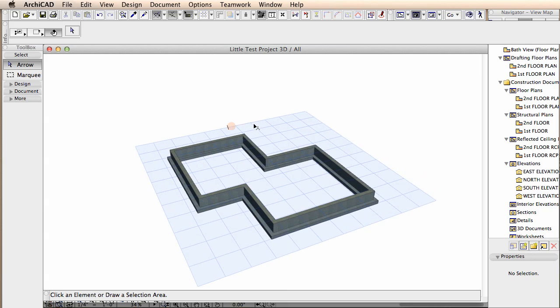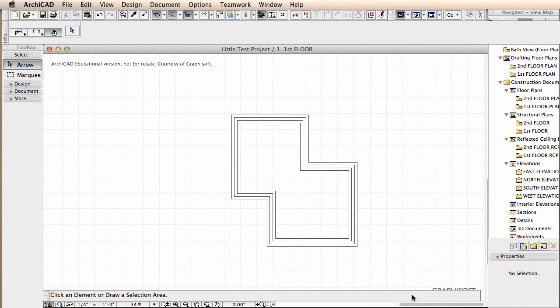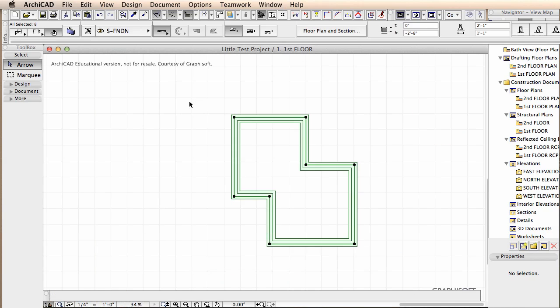Now, if you see any other objects in here left over, maybe there's cabinets on the ArchiCAD layer, be sure to choose the appropriate layer that they should be on. Select the objects and choose the appropriate layer. I'm going to get back into Plan View here, and I'll select all of these objects here, which